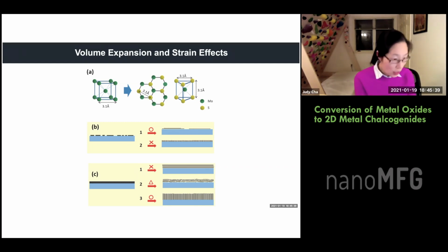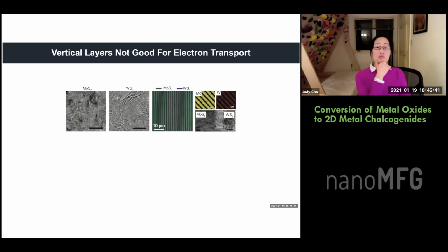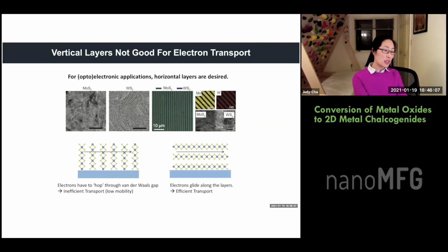Yeah. So that's sort of our journey about converting metal films into chalcogenides. The idea was good, and the idea was that if we can just react metals, we already know how to do large-scale heterostructures of metals, and then you can make a one-go sulfurization or tellurization to make heterostructure TMDs. Yeah, but it's polycrystalline, and if it's thick, you're going to make the molecular layers standing vertically.